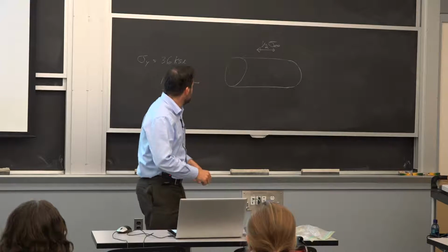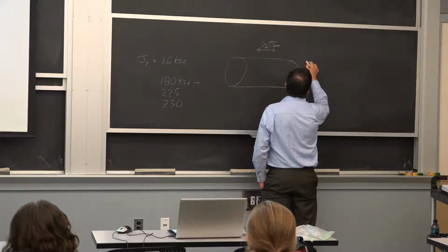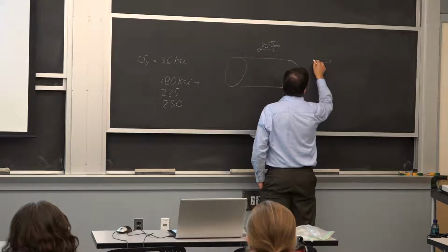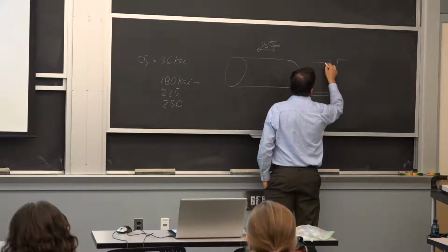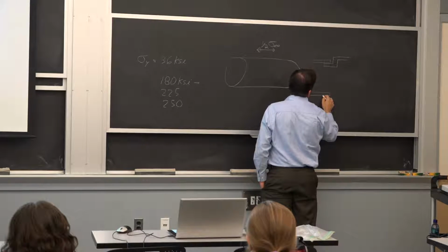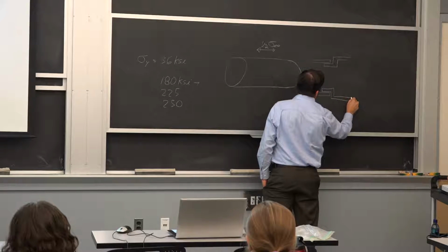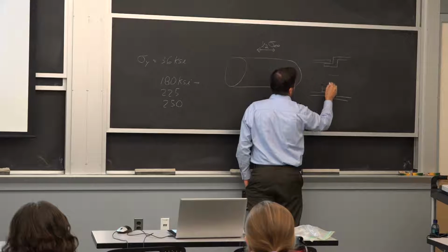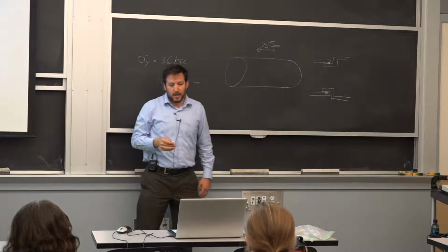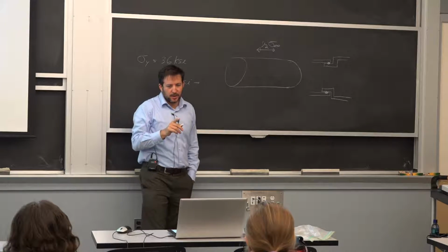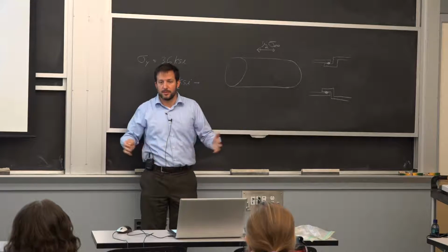So they make the joints of the cylinders essentially a bell and spigot, they call it, so that there's going to be a member on the outside. Looks like this. Then you have a member on the inside coming in. Then you put a big O-ring in here, so it's able to move a little bit. Now, of course, you need a mechanism so it can't go too far on the long scale.